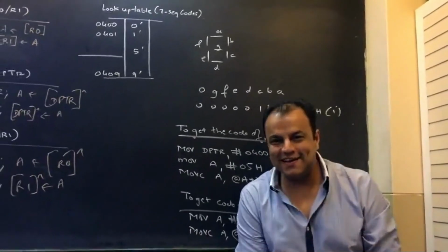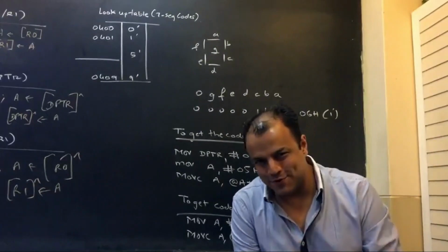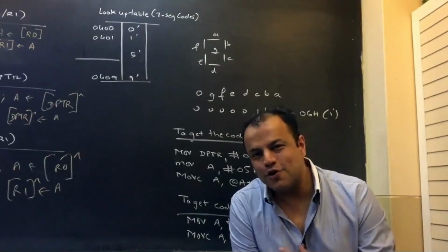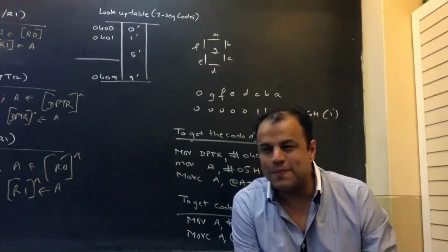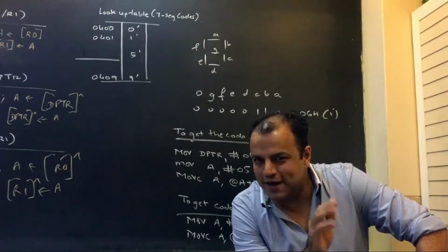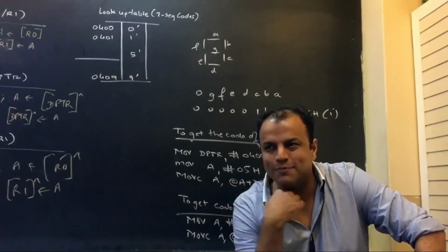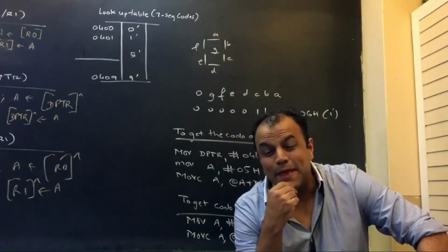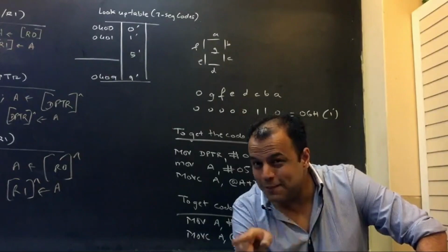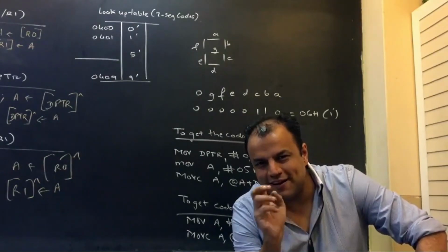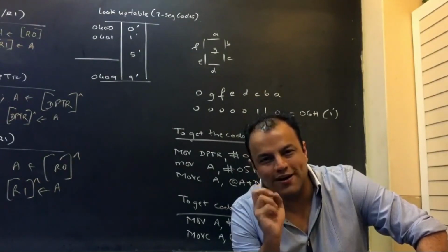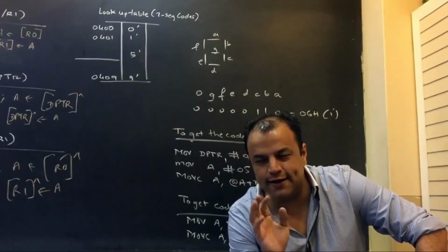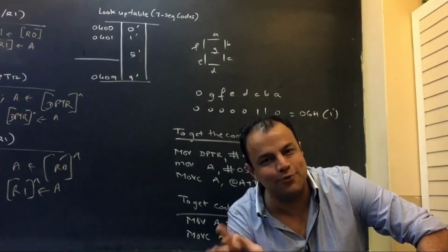So we are discussing index addressing mode. Index addressing mode of 8051. It is for ROM. Okay, only for ROM. Now, ROM is called program memory. RAM is called data memory. So that means you store data in RAM and you store programs in ROM. But ROM doesn't contain only programs. ROM also contains some data. What data? Static data. Data that we don't want to change. Hence you store it in ROM.